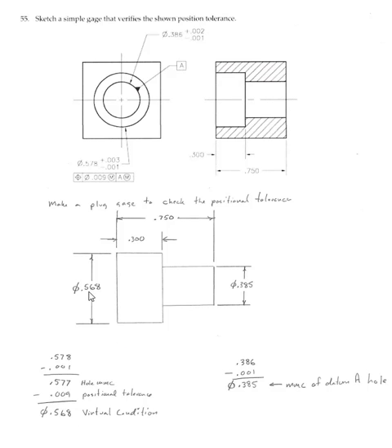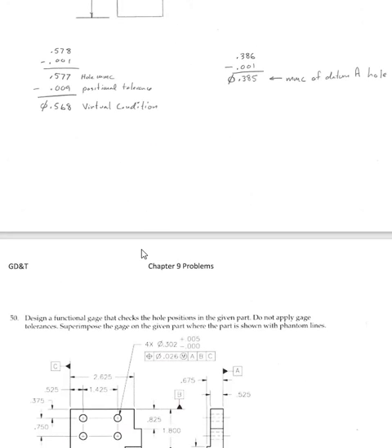So if this plug is able to be inserted into this hole, then I can say these two features meet that positional tolerance.